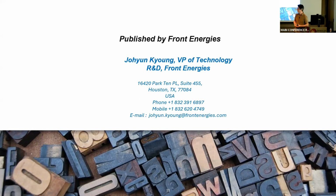Any other questions? I'm wondering if these offshore structures are feasible in the Gulf of Mexico, given the extreme hurricanes that occur pretty frequently here. Yeah, right. One of the design load cases considers that kind of wind environment. Under hurricane conditions, the turbine cannot produce power. We call it the parking condition. They change the pitch angle to the weather vane feathering state and the rotor does not rotate. So it is fixed and just endures the environment. We consider that.